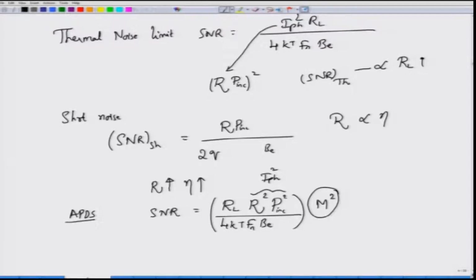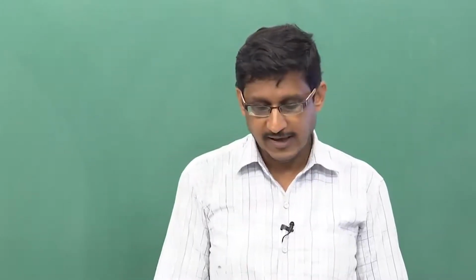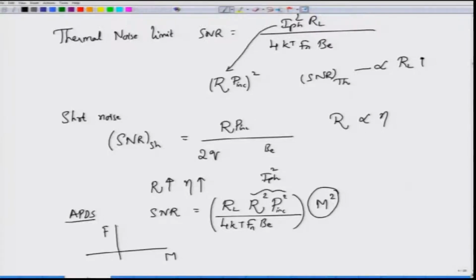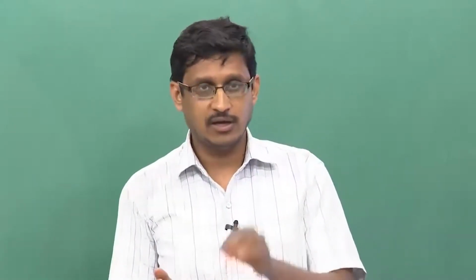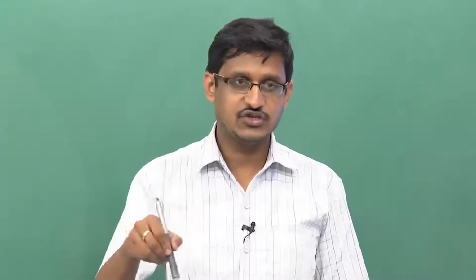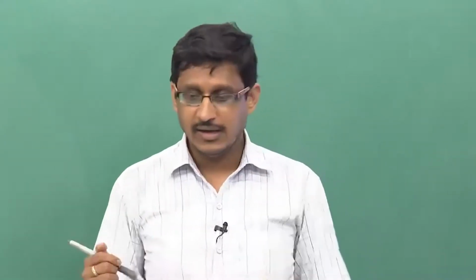So, if you want to increase SNR, you can increase SNR by operating the APD with a larger multiplicative gain. However, larger multiplicative gain also has some effect on the excess noise factor F, right, because we have seen that F versus M curves for an APD depend also of course on the additional factor k, but in case you look at it, they are actually linearly increasing for larger value of k. So, there is actually an optimum value of the multiplication factor M, which makes the SNR highest. For a given optical input power, you can maximize this multiplicative gain, which you can obtain by going back to the noise variance and then differentiating that with respect to M and setting the resultant expression to 0.